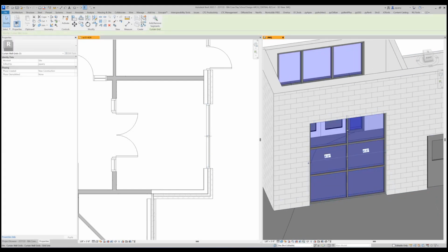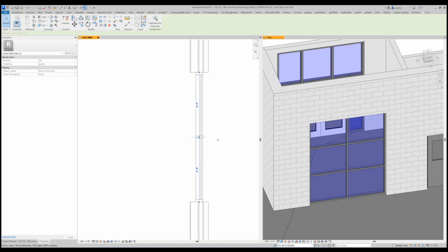You can do it from plan view or from 3D view, either one, or you can do it from elevation too, but sometimes it's harder to figure out. So this is the first thing. Let's deal with that 1'4" and 1/8. The good thing is that 1'4" and 1/8 is going to the center of that mullion, which is important. This is another huge part of this.